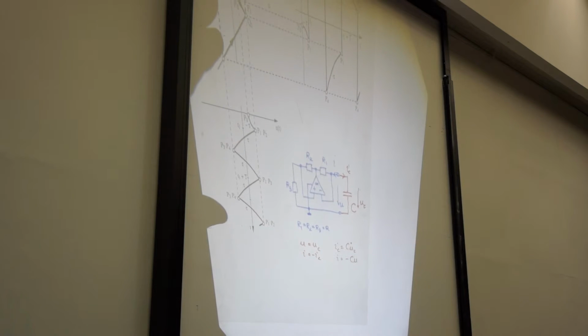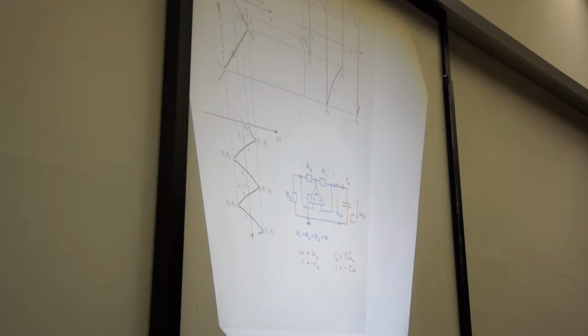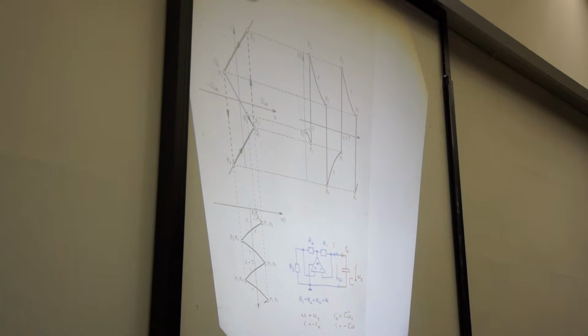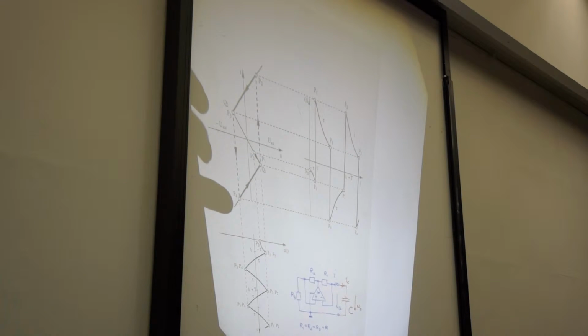First-order circuits: we have been dealing with nonlinear, piecewise linear circuits, and we first looked at a circuit where that piecewise linear characteristic is constructed with an operational amplifier with these three branches, where it's modeled with the positive or the negative saturation voltage, and with the three resistances we basically get this S-type shaped nonlinear resistive characteristic.